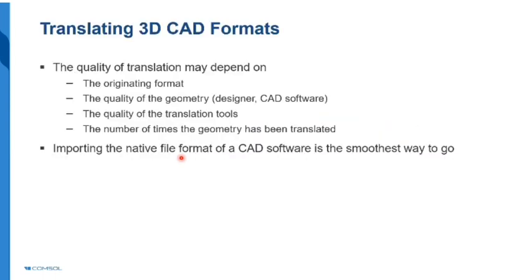When you are bringing any imported CAD into COMSOL, one needs to ensure that you are getting good quality CAD. Good quality in the sense that it does not have unnecessary details present in the geometry that you are importing. But the quality will also depend upon various things, such as the original format that you are importing.